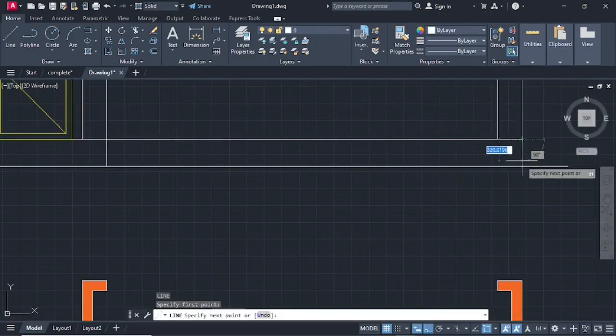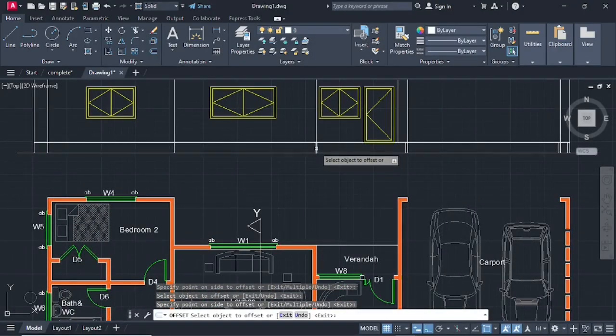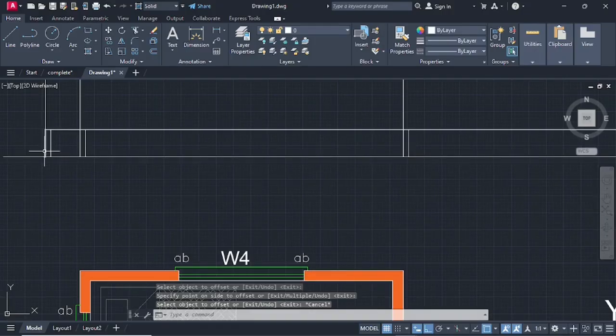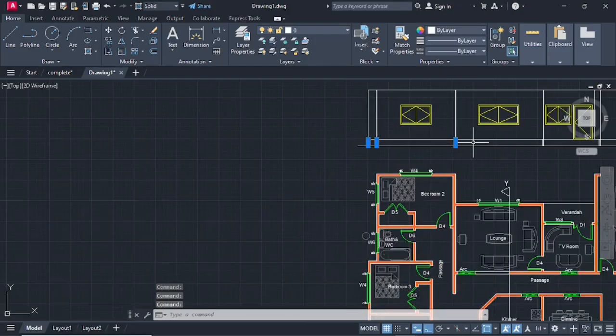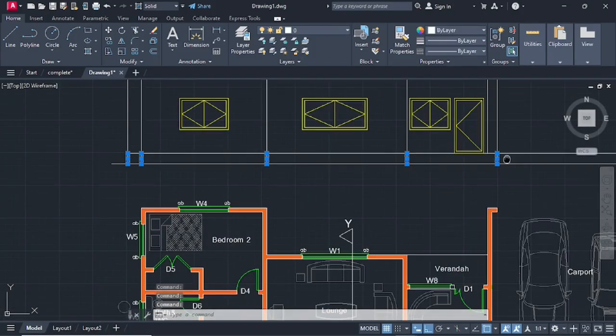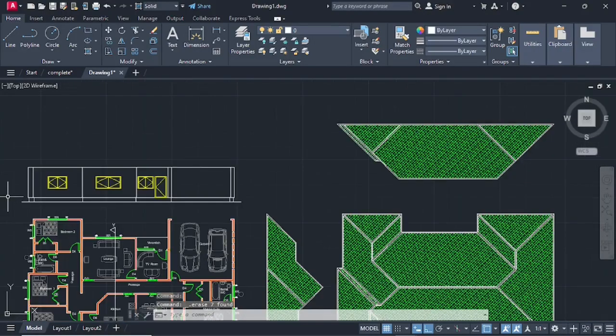make a line here, enter, a line there, press on enter, that, then go on offset at 80, press on enter, then you offset this side, offset this side, offset this side, offset this side, offset this other side, then select this line, that line, that line, that line, select this line, select this, that, and delete, just to show that this down here it's our DPC.